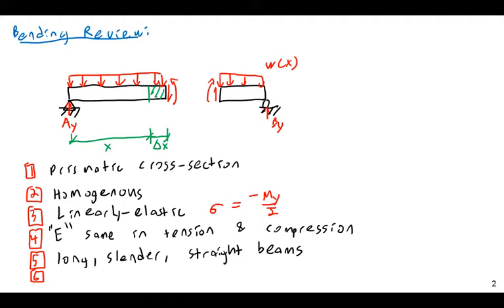But in reality, what we call point loads are something like, my go-to example, imagine you have a 20-foot long beam and a weight hanging from a chain or metal cable draped around it, and maybe this cable is only half an inch thick. Compared to the 20-foot long beam, this half-inch thick cable essentially has zero width. When you actually apply loads to real structures, you always apply them over an area.